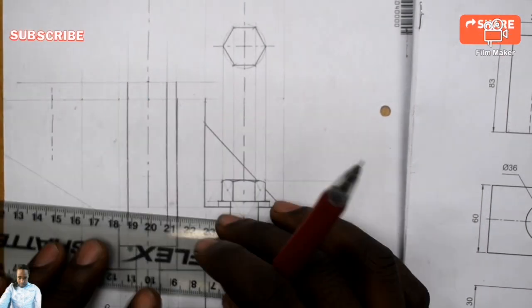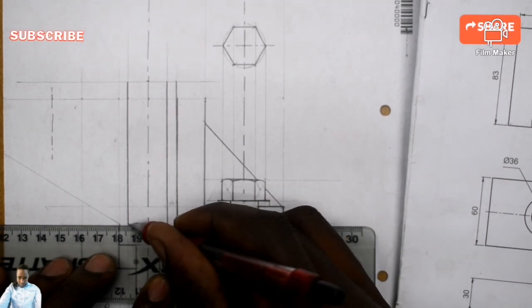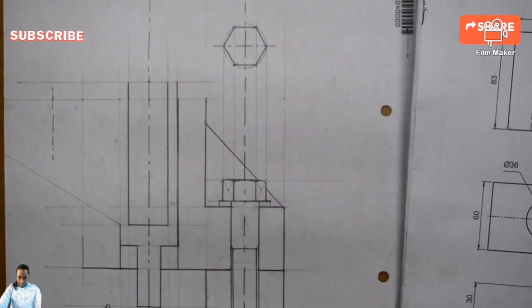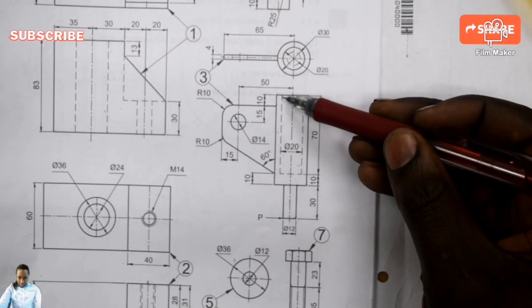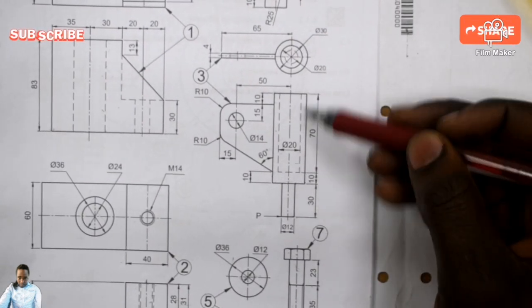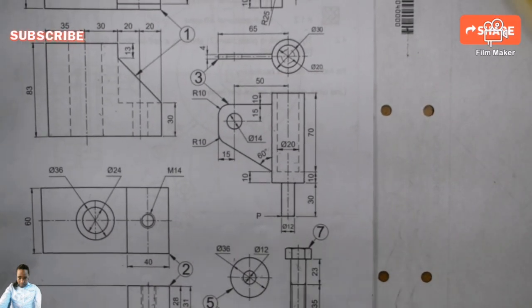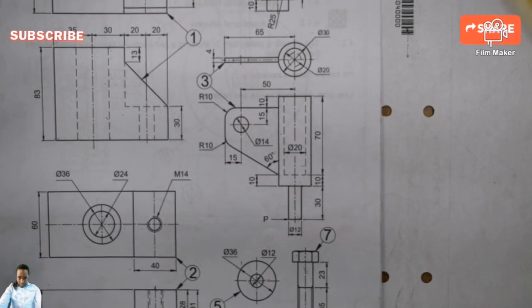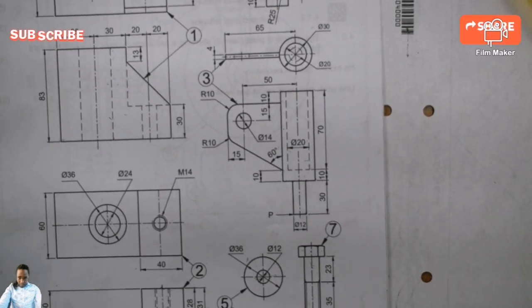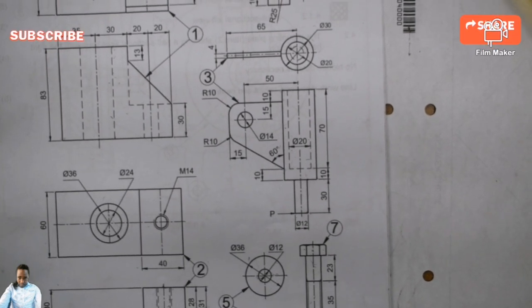So these were hidden. These were the hidden details of item 3. So now they become dark. This one, it will become dark because we cut to expose the inside view, isn't it? We cut to expose the inside view, and the hidden details will become solid, or dark lines.